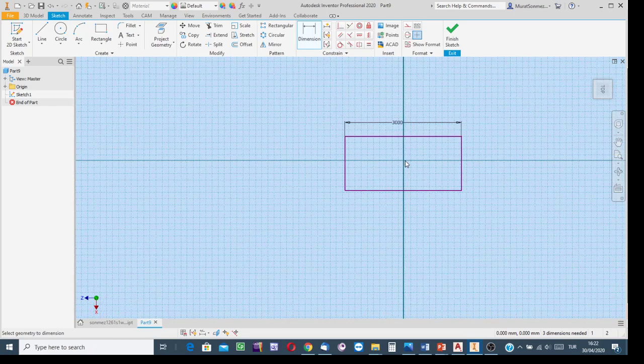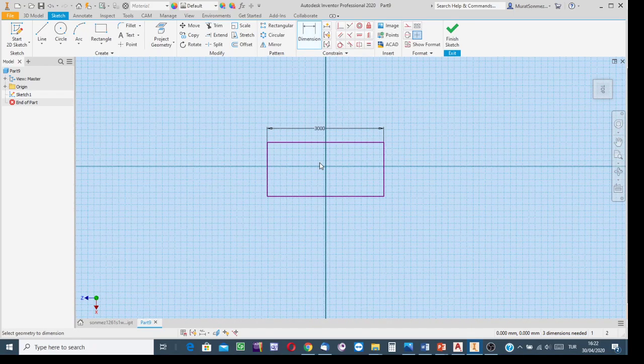In Inventor, since I selected the ISO standards metric unit system, the numbers are in millimeters. And in this direction, say that the washing room is 2 meters, 2000. Okay, these are the edges of the inner surfaces of the walls.